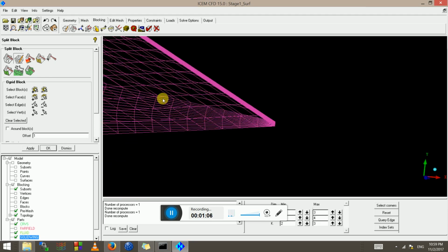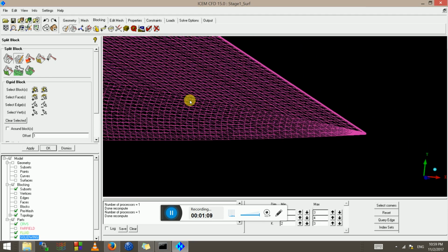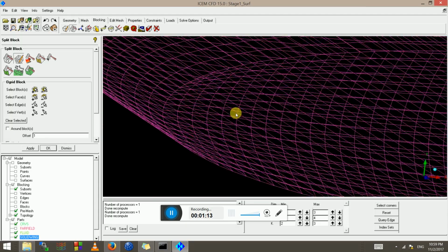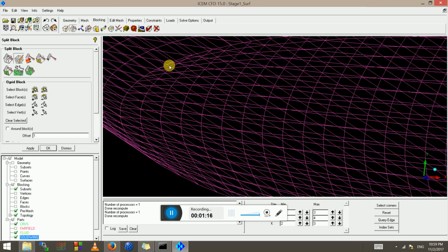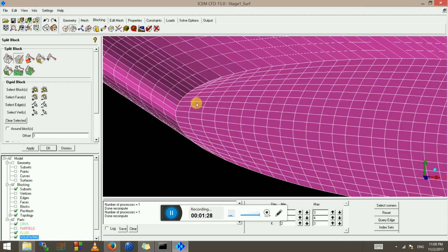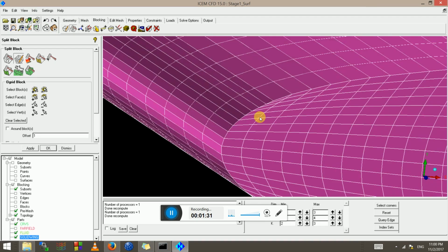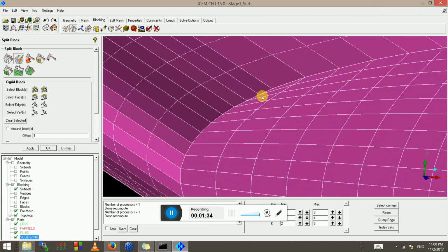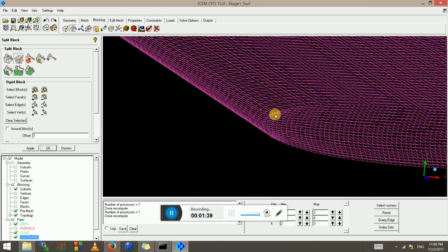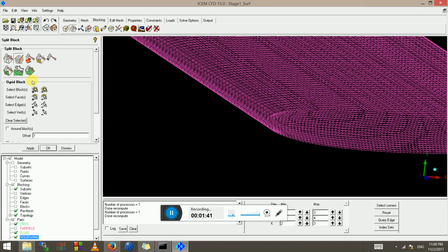One more thing we want to take care of. After doing all the spacings, like I said in the previous tutorial video, we need to remove the misoriented cells, the cells which do not look very square type. If I go into solid view, it's a better view of what's happening. Let's go ahead and do that actually.